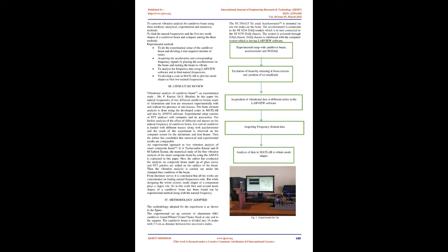It is important to know the mode shapes of a component, especially when it is being designed to stay inside another hollow component. For example, consider a gearbox. It consists of gears and shafts inside the casing. To design the casing efficiently, the designer should be aware of the different mode shapes of the components inside. So, the designer can accommodate space in the casing for the gears not just in the static conditions but also during resonance.